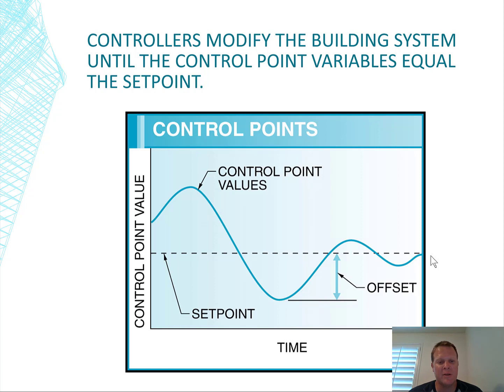And so in speaking to the client, when they're looking at their HMI, if they're not familiar with it, they might think, oh, this is so far beyond. No, we just switched modes. And so over time the programming is going to get to that control point pretty close, but I would expect some offsets from the actual set point while it changes modes or while the equipment starts up, right?